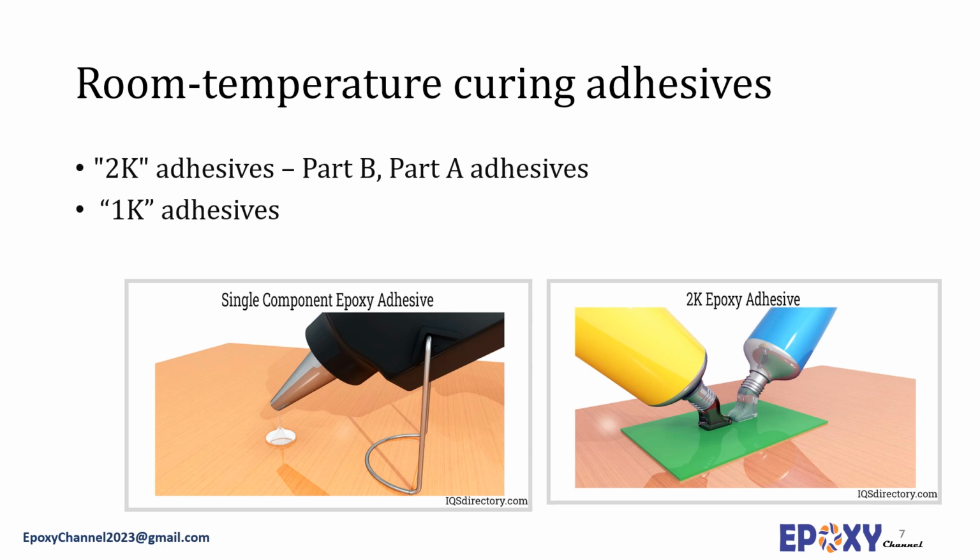It is also possible to cure the room temperature curing epoxy adhesives at elevated temperature if faster curing is required. Polyamide or amidoamine curing agents are often used in these systems, and the base epoxy resin is a liquid diglycidyl ether bisphenol A resin. Other formulations may contain aliphatic amines, catalytic amines, amine adducts, or sulfur-based curing agents such as mercaptans. Two-part room temperature curing adhesives are generally preferred for large parts, as the energy consumption to heat the substrate for curing might be huge.